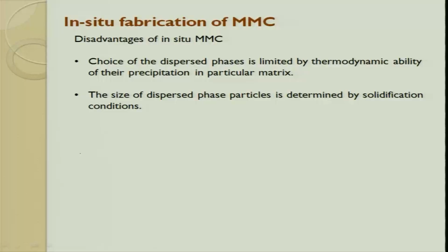The disadvantages are that the dispersion phase is limited by the thermodynamic ability of its precipitation in a particulate matrix. The size of the dispersed particles is determined by the solidification condition. So, these two I do not have control over. Not many materials give me this thermodynamic ability. The second thing is that I cannot decide what particle phase is getting formed; it evolves. So, I have to live with what is getting generated.